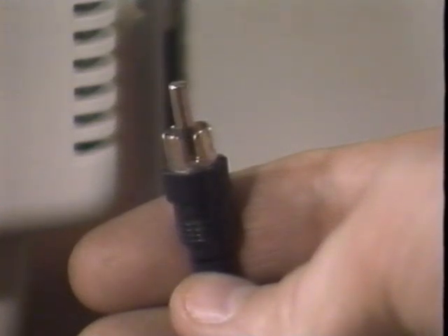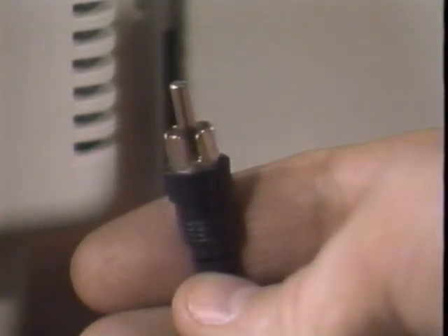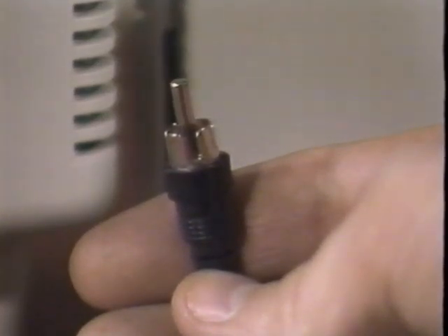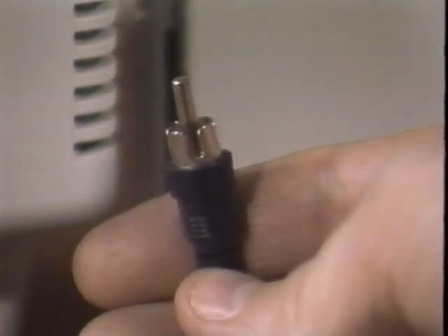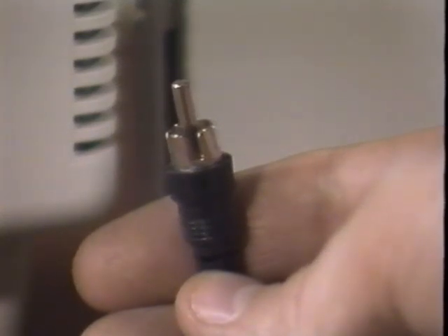A composite video connector brings all of the signals that the monitor needs on a single pin: horizontal sync, vertical sync, video information, and, in the case of the color monitor, color burst, all pass to the monitor through a single RCA jack. The composite connector is the same for color and monochrome systems. The other two main types of video input, direct and RGB, both use a DB9 connector. This is a bit misleading since their pinouts are somewhat different.